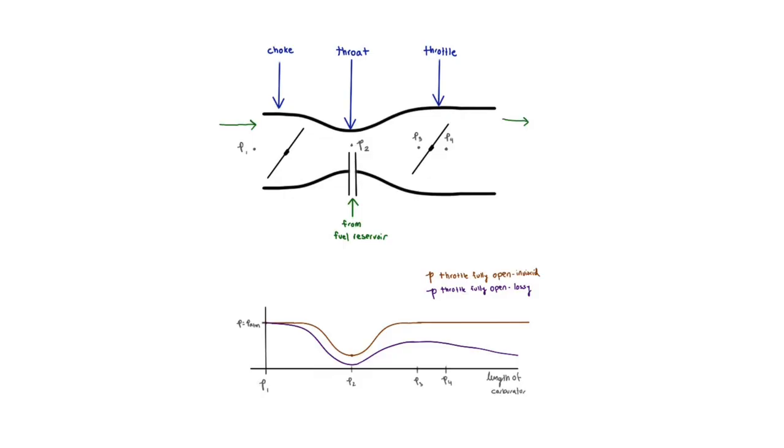Comparing the solution we got to the solution you would get without doing a lossy analysis, it becomes clear why a lossy analysis is critical to properly understanding the system and how it functions. As shown in this plot, a lossless analysis concludes that the manifold pressure would approximately equal atmospheric pressure if the areas at the beginning and end of the carburetor are the same, which is incorrect.